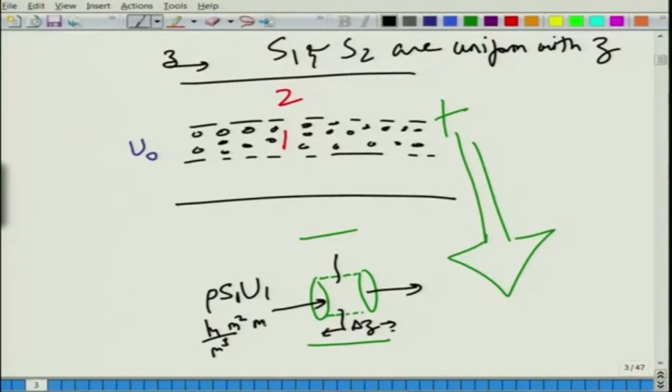This has unit of meter per second. So, these cancel, you are left with the unit of kg per second. So, that is your mass flow rate, rho S U. Remember your elementary fluid mechanics. So, rho S1 U1 at Z, and the one that goes out from the opposite surface is pretty much the same form, but this is evaluated at Z plus delta Z. Okay.